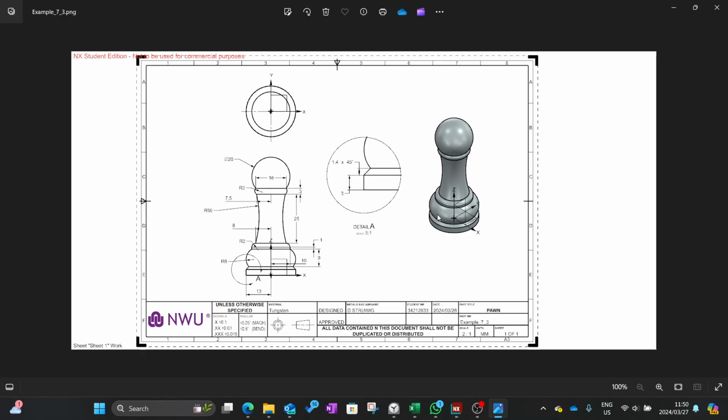So essentially revolve is by taking a sketch feature and then extruding it about some point and around some vector or axis. So for this model, only half of the sketch was drawn, and then it was revolved about the z-axis, or around the z-axis about that sketch origin point. So once again, it's important to note the position and direction of your sketch origin, as this will influence your center of mass that you need to enter.